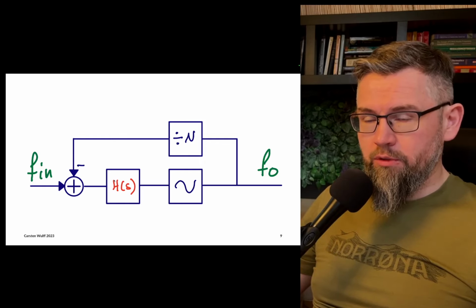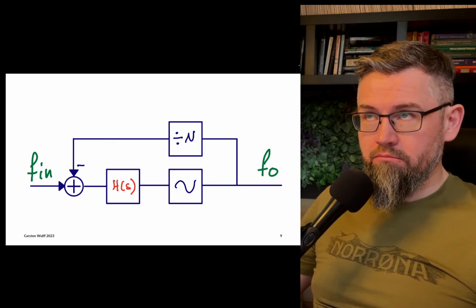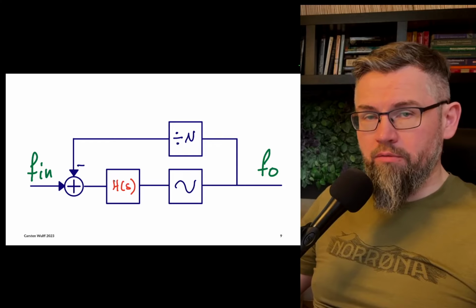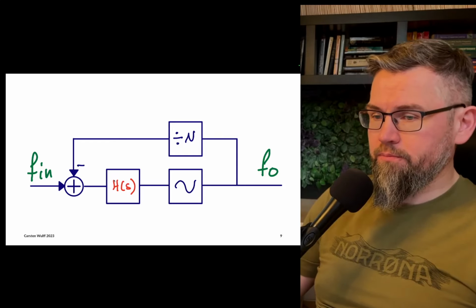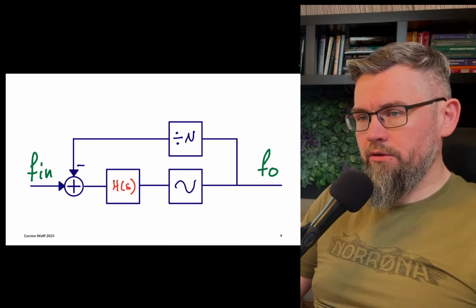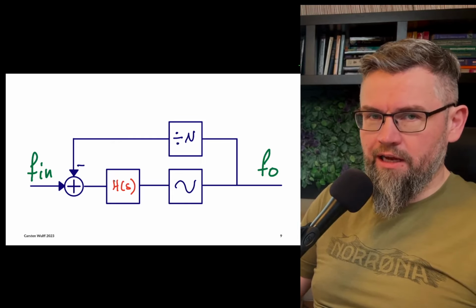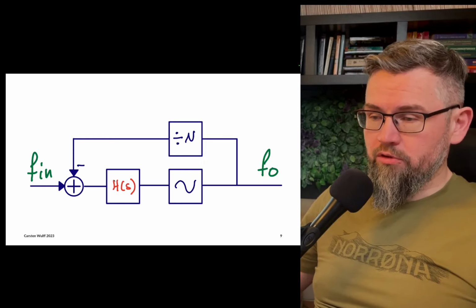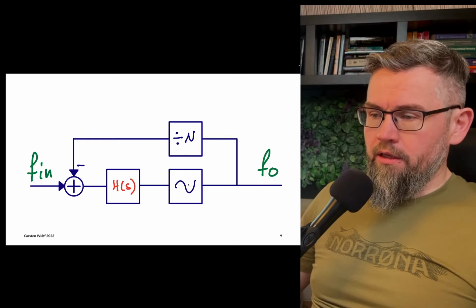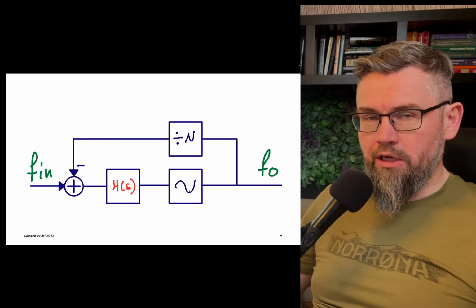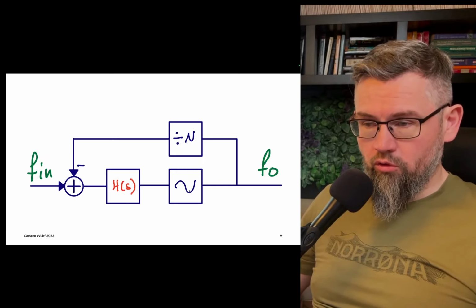You can also do this with delays, and there's a link in the syllabus to a paper on delay lock loops. And they all have different applications, whether you need phase aligned or when you need delay, or you just need roughly accurate frequency. And also in a PLL, it is possible to make the oscillator that generates the output frequency digitally controlled.